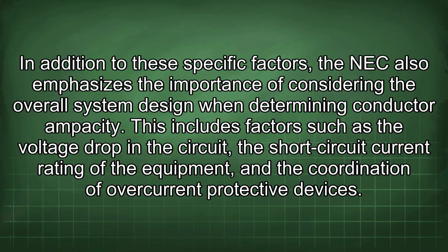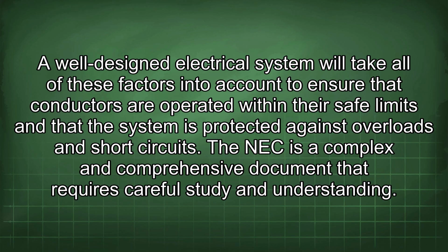This includes factors such as the voltage drop in the circuit, the short circuit current rating of the equipment, and the coordination of overcurrent protective devices. A well-designed electrical system will take all of these factors into account to ensure that conductors are operated within their safe limits and that the system is protected against overloads and short circuits.